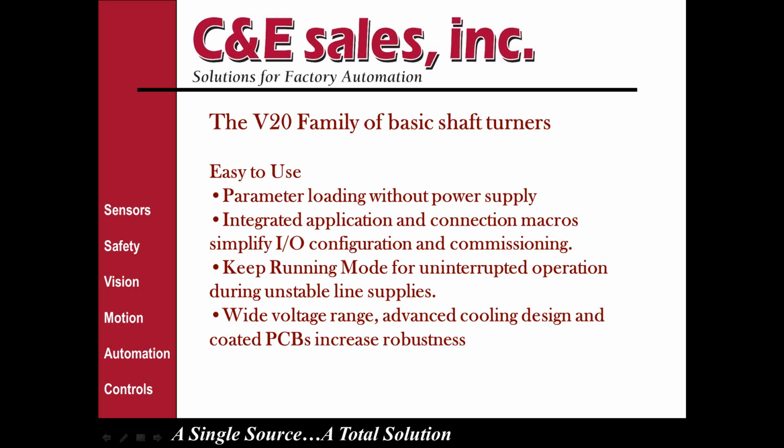There are connection macros, as we mentioned earlier, and application macros that really help in setup, configuration and commissioning. There's a keep running mode, which looks at power fluctuations coming into the line, and in many cases will help ride through those fluctuations to keep the drive and system running. And there's a wide range of voltages available, and the cooling design, especially with the push-through, makes it a very robust application.